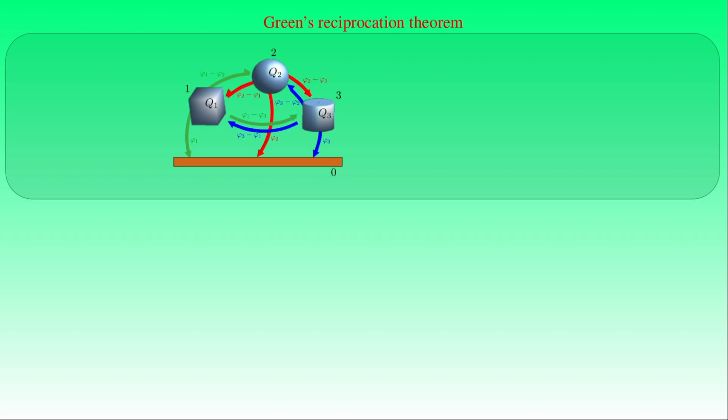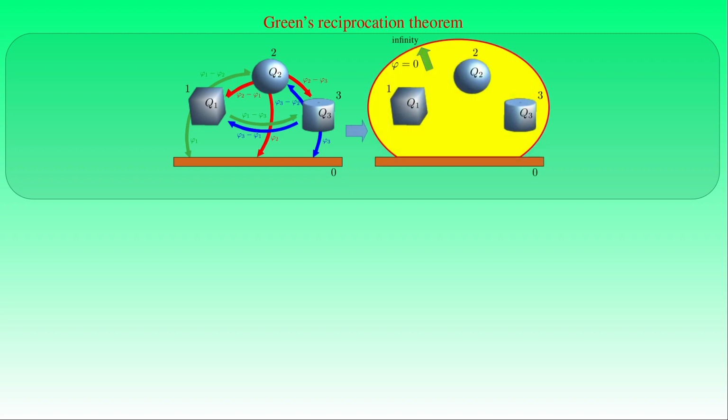However, even in the general case, the finite amount of charges Q1, Q2 and so on distributed over the surfaces of the conductors 1, 2 and so on are localized in space, and the electric field produced by these charges vanishes at infinity. Therefore, any imaginary equipotential surface S0 of 0 charge and 0 potential at infinity joined with the Earth or the electrode 0 can be considered as an uncharged conducting surface that encloses the system of charged conductors. The union S of the conductive surface S0 and the boundary surfaces of the electrodes 1, 2, and so on, denoted by S1, S2 and so on, forms a boundary of the volume V enclosing the region of the system of electrodes but excluding the electrodes themselves.